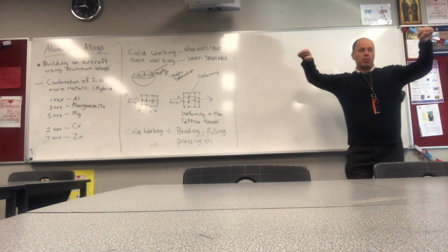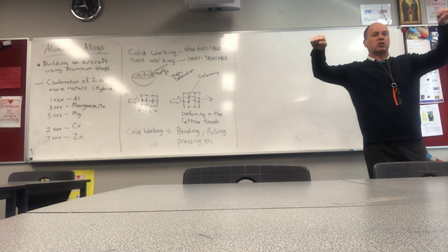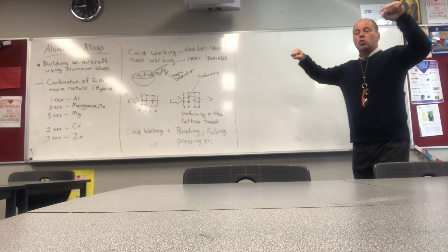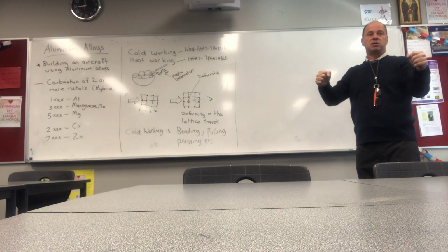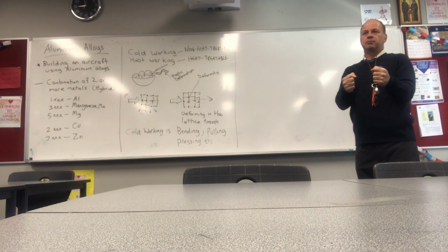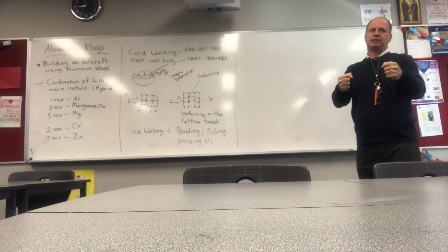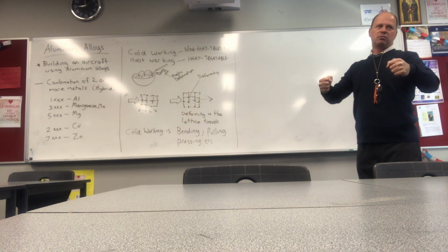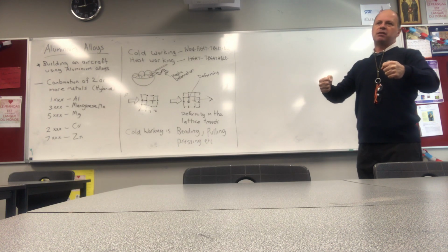So you can grab a copper pipe. You can actually try this if you ever get a piece of copper. I've got some at home. I might bring it in to show you. I'll bring a few pieces of it in. When you bend your copper pipe the first time, pretty easy. Then you try to bend it back, and all of a sudden it's changed. The material has magically become stiffer.